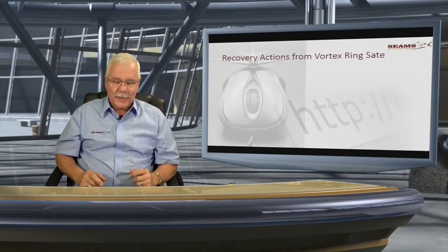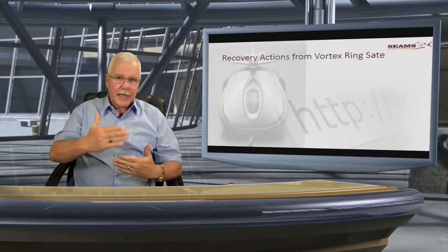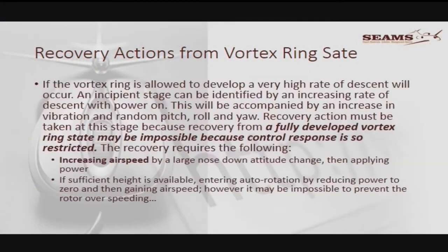I don't think so. So remember, it's one thing to look at the aerodynamics, it's another thing to put ourselves in the practical environment. So how do we apply this? Good. In the vortex ring stage, allowed to develop, very high rate of descent. Its incipient stages can be identified. Because recoveries from a fully developed vortex ring state may be impossible because control is restricted.